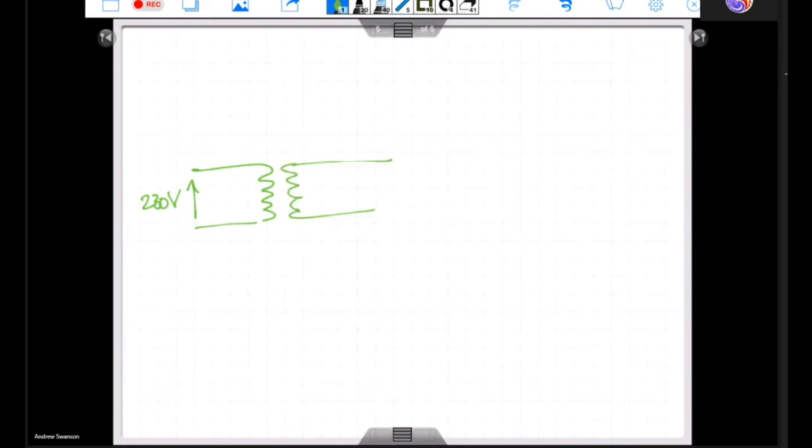So again, let's draw it out a little bit. Let's say we've got a 100 nanofarad capacitor. Let's say it's representing an 88 kV cable. Right. So that's the V line. Our V naught would be equal to 88 divided by root 3. That's 50 kV.